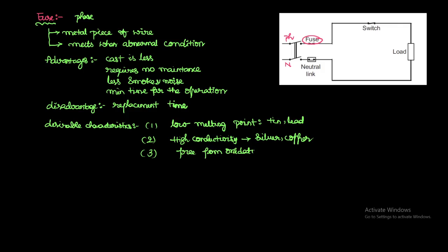Whenever iron is exposed to water and the atmosphere, it gets some rupture, that is called oxidation. Silver is an example of a material free from it. Fourth, it should have low cost, which is the main important point. Silver is somewhat costly, which is why lead, tin and copper type materials are used as the fusing element. This is the information about the fuse.